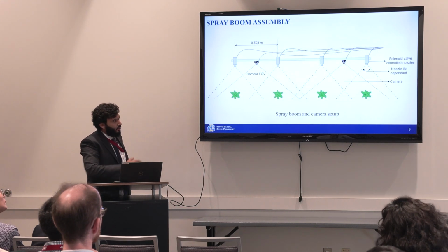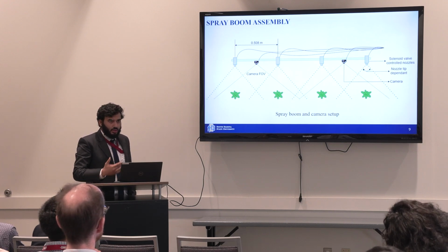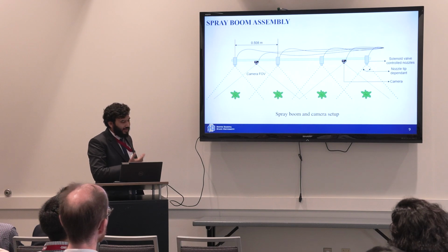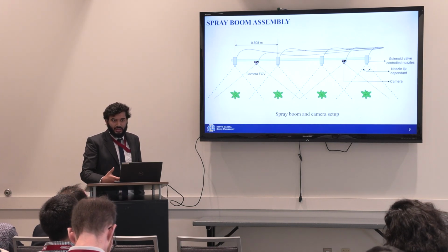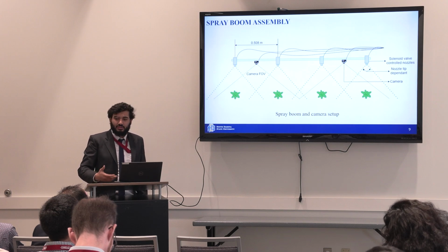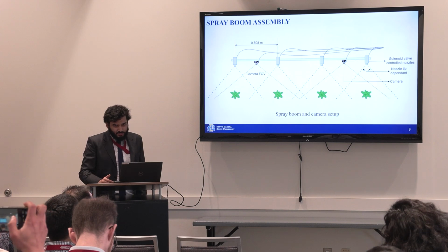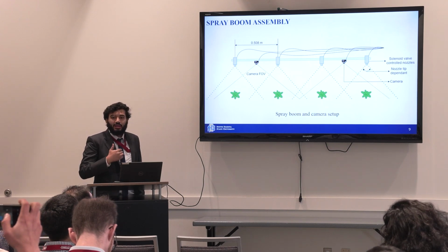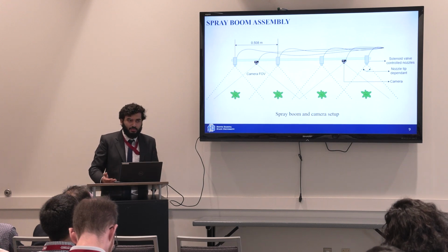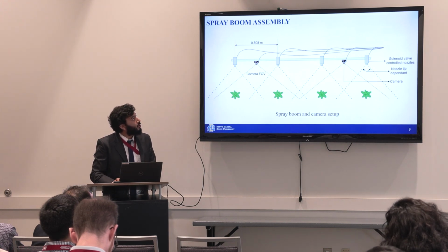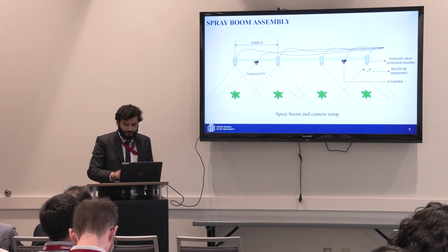This is the schematic of the boom. We chose 2 cameras and 4 nozzles right now. So one camera can control multiple nozzles. And the system which we developed, the algorithm, can handle more than 1 camera as well. This tells us that it is scalable. Due to a small computer and at a test stage, we just chose 2. It can be scaled up to handle more cameras and more nozzles in the future. We chose 0.508 meters distance, which is standard right now.